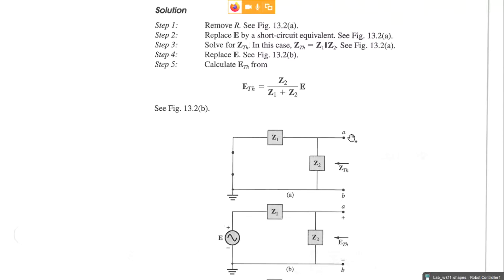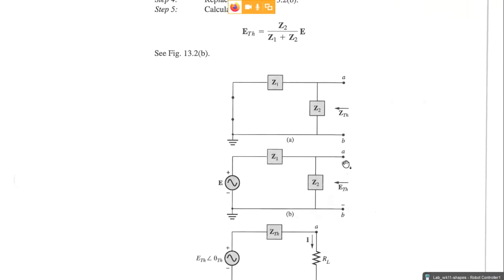So what we've done is we're breaking the circuit at 2 points, and then we're going to find the impedance over to the left of those, or of the part that we want to find the Z Thevenin for. And then we're going to find the voltage drop with A and B open. We just want to measure the voltage here and get the voltage drop.